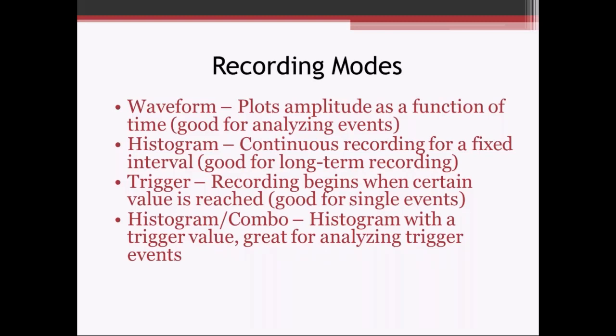Some of the different recording modes that we can use. Waveform recording mode, that's the typical wiggle trace that you see, which plots amplitude as a function of time. It's really good for analyzing events. You can take a look and see, is this a transient event? Is it a sustained event? And maybe even evaluate it a little bit more using some other analysis to see what the source is.